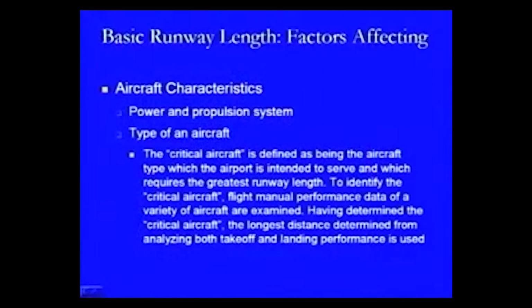Now, another effect is the type of aircraft. When we are talking about the type of the aircraft, there is one technical notation which is used, and that is critical aircraft. The critical aircraft is defined as the aircraft type which the airport is intended to serve and which requires the greatest runway length.